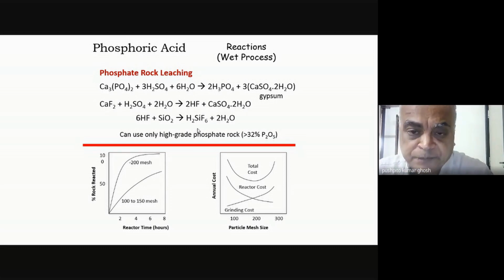That's one. The higher temperature is also very important because these phosphate rocks come as rocks, and then they have to be ground. Now, if, for example, I want to operate at a lower temperature, then I must necessarily grind it more fine just so that I have a higher surface area.